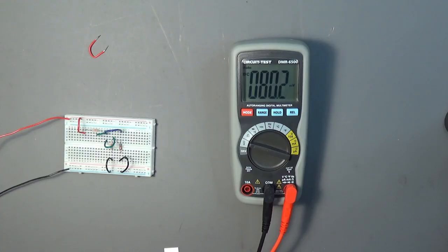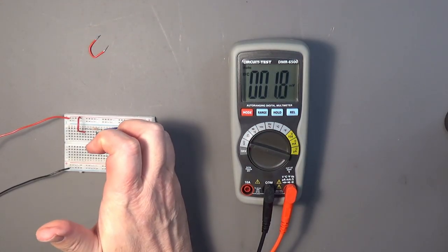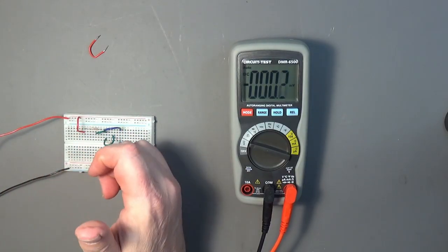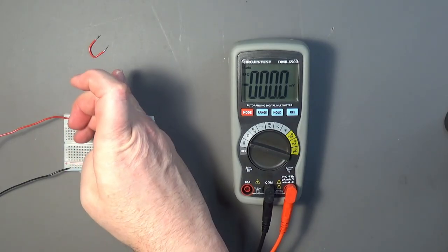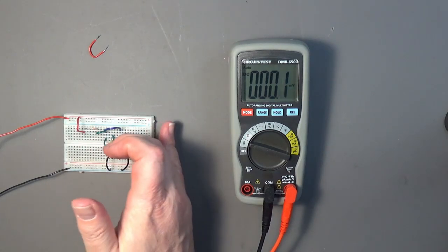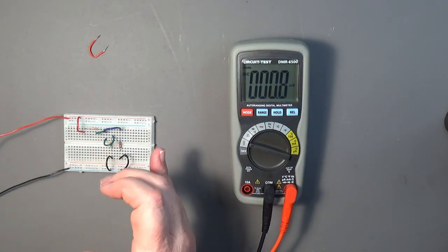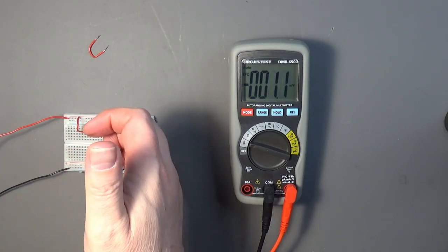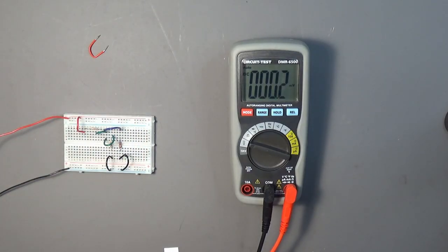So, like we've seen before in our parallel circuit, the voltage drop across both of these in parallel is the same. The voltage drop across our two, so this effectively is one resistor, is different. And it depends on how big the resistor is. Now these two together are about 1.6K, so it's going to be a little bit different, and it is. It's about 5 and a bit, and that's 3 and a bit. So together they add up to 9. So that's our voltages in this circuit.